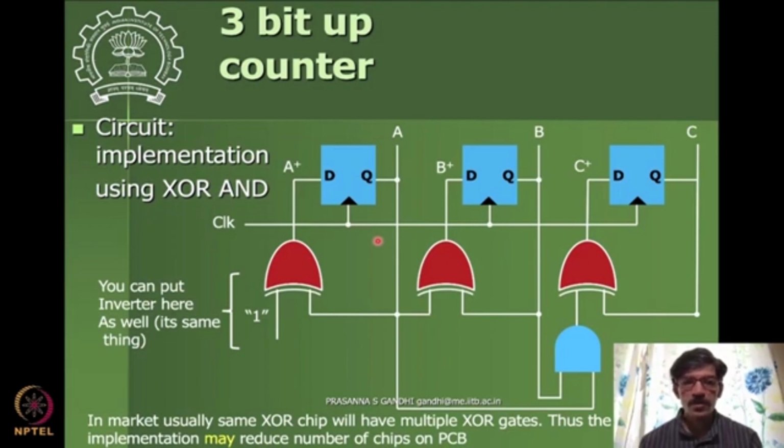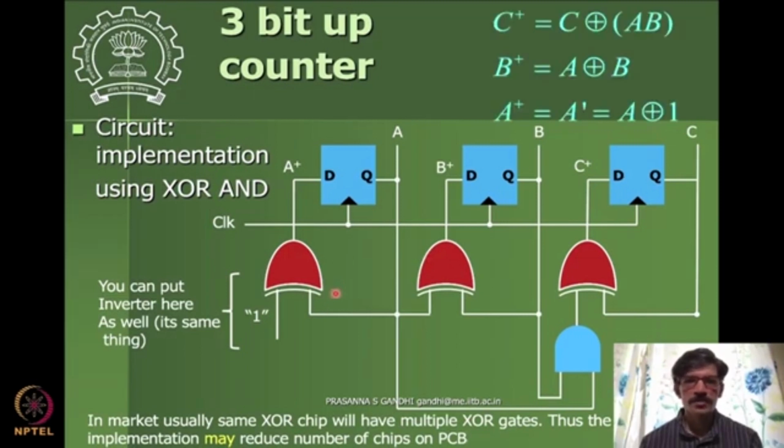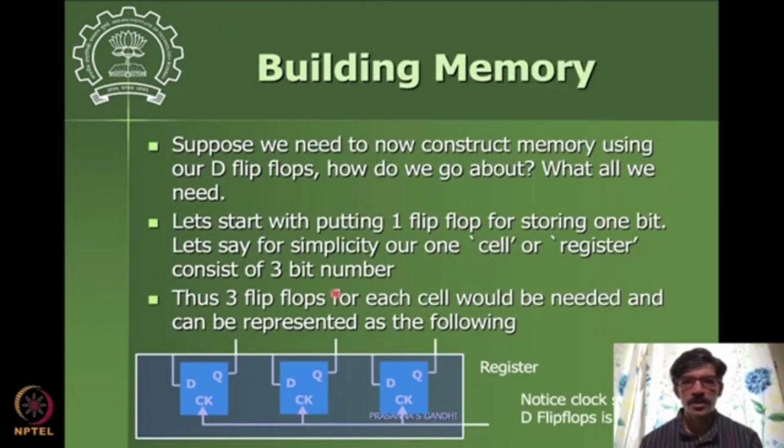So this is how we go about developing these counters or sequential logic circuits. Now we want to build memory, so we'll talk a little bit about memory. Say a 3-bit memory: we need to remember 3 numbers, so we need the 3 D flip-flops to be combined together.